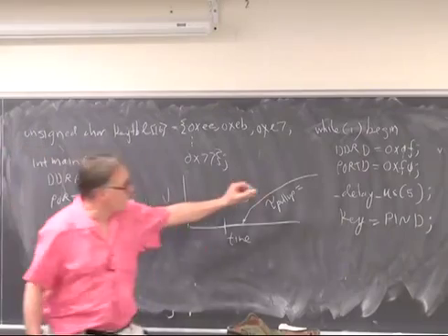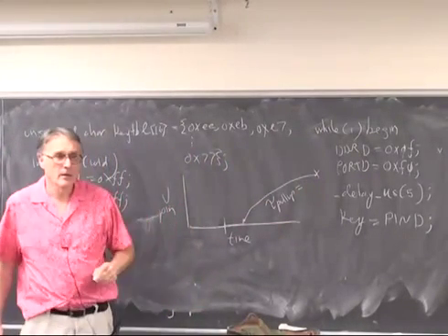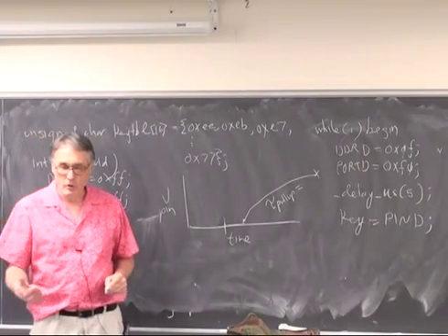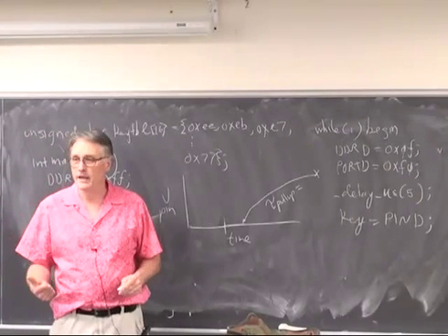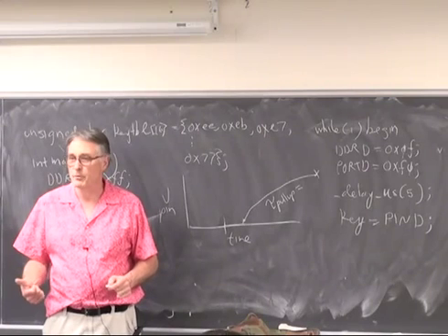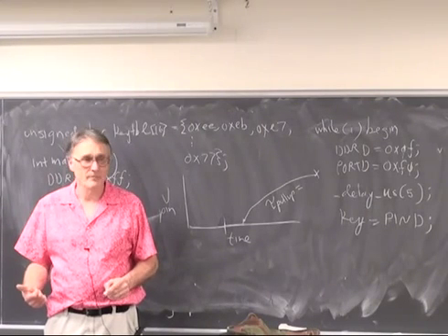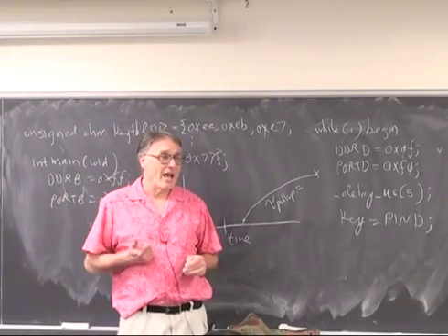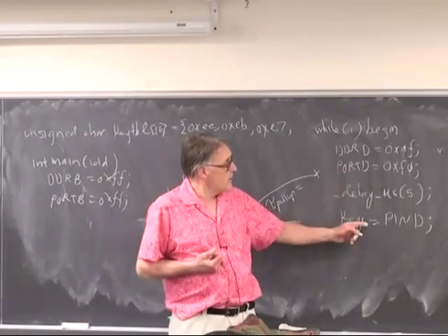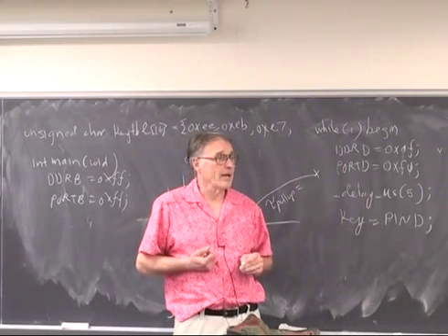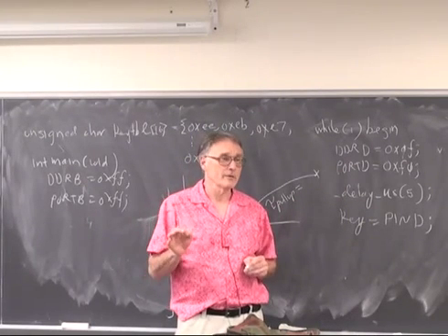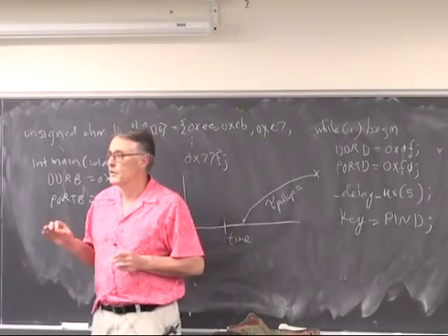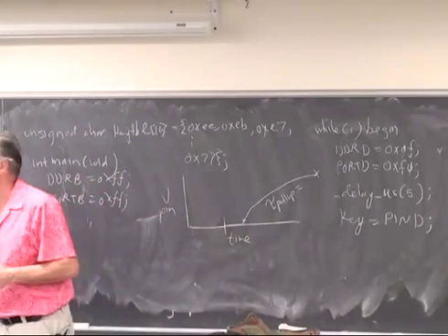And I want to be up here because the code assumes that the pull-ups are turned on and the outputs are high, or the inputs are high. Inputs are high before the button is checked. And so what was happening is that when I read this without the delay, I made a very awesome random number generator because all of the inputs were still floating at some random value.